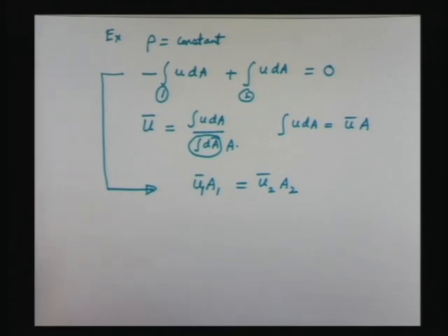This is like your so called A1 V1 equal to A2 V2. Okay, so this is very important. We often see that if a student is asked what is the continuity equation, he immediately says A1 V1 equal to A2 V2. The first important concept that you should convey to your student is under what conditions this is valid. We have started with the general continuity equation and we have simplified it to a special condition. That must be ensured. The second thing is the meaning of V1. When you write A1 V1, V1 is not the velocity at a point. V1 is the average velocity over a section.